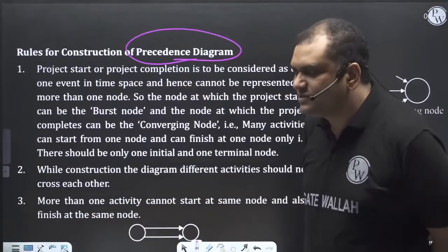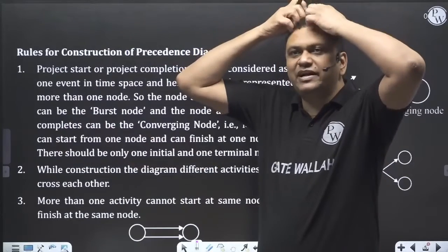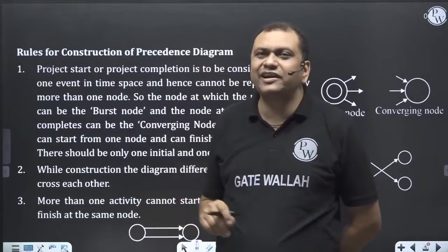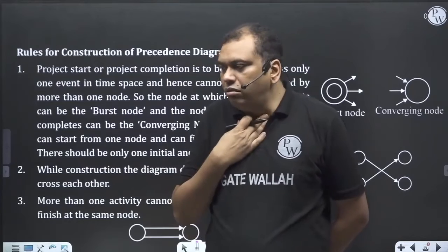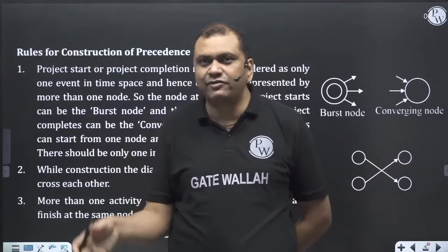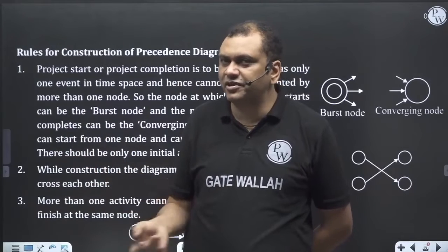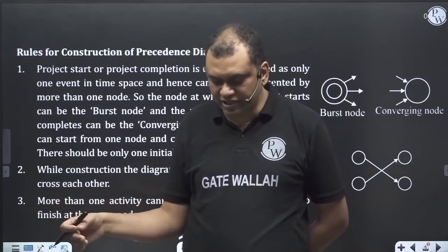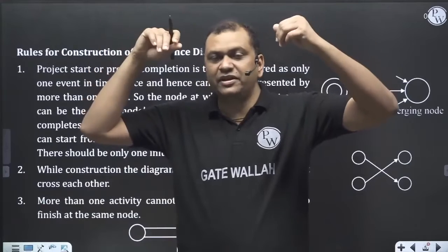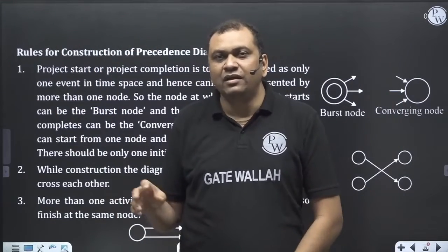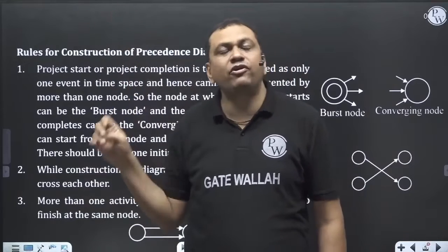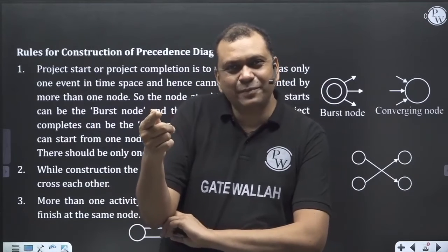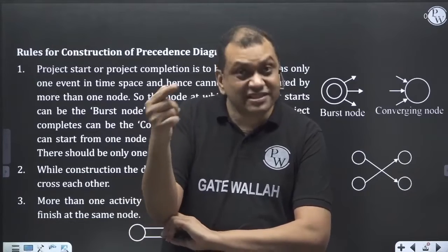Suppose there is a construction of a building. There are different activities. First activity, let us say, digging the foundation: an excavator comes and digs the foundation. It's an activity. Then the construction people will come to lay the foundation. Then the slab is another activity. Construction of the wall is another activity. After that, there will be cementing of the wall. After that, painting. So painting is a successor activity, and cementing the wall is a predecessor activity.